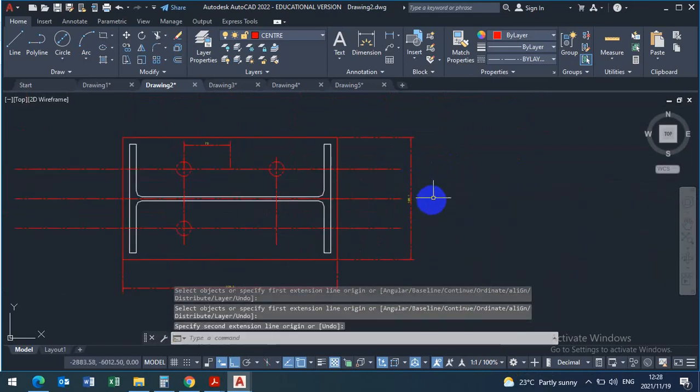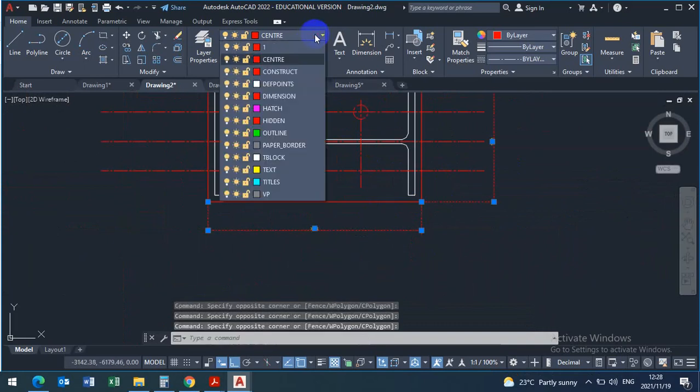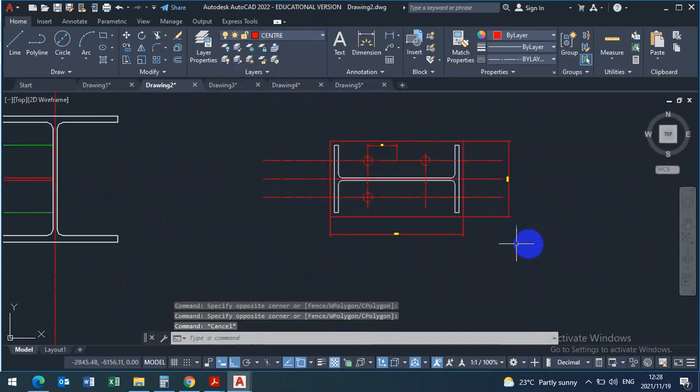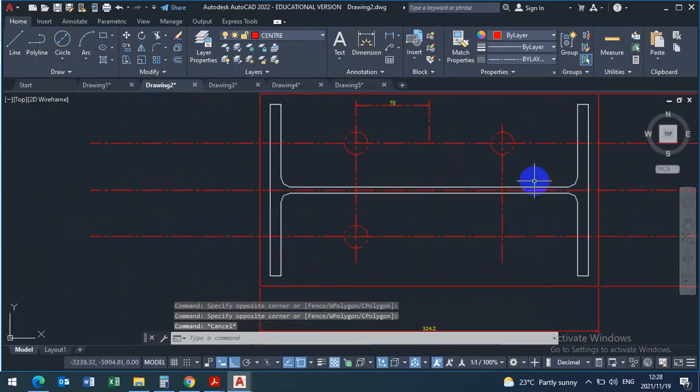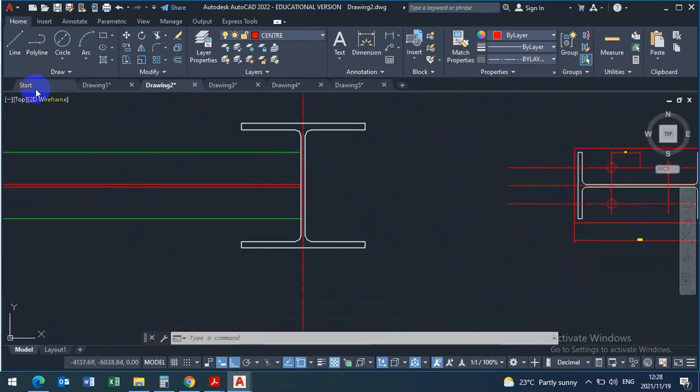And make sure that when you do dimensions, they must be under dimension layer. Don't just dimension on center layer, dimension layer. But we need to scale down the drawing and then we do dimensions. I want us to now come and show the thickness of the end plate here. You first project the end plate. Okay, you draw a line, that is the end plate.